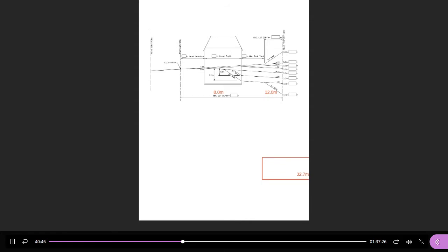Another thing you need is minimum backyard. So this is the space where you're going to put your picnic. You want to make sure you have at least a usable backyard. The depth for that typically is 7.5 meter minimum. Okay, that's minimum. So 8 meters the front, 12 meters for the house, 7.5 minimum usable backyard. Those three numbers are fixed. Everyone's going to use those three numbers.